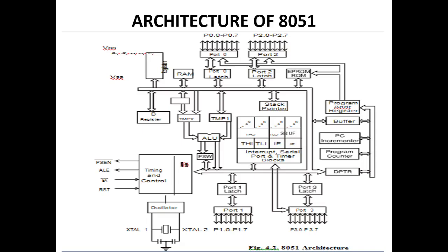Next, serial port. The 8051 has a full duplex serial port, which is software configurable in 4 basic modes: shift register mode, standard UART mode, multiprocessor mode, and 9-bit UART mode.